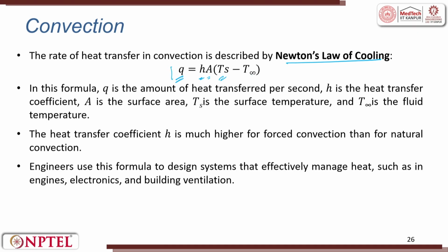So, by using this you can calculate. We saw Fourier's law of conduction, and for convection we have Newton's law of cooling. The heat transfer coefficient h is much higher for forced convection as compared to natural convection. Engineers use this formula to design systems and make them energy efficient.